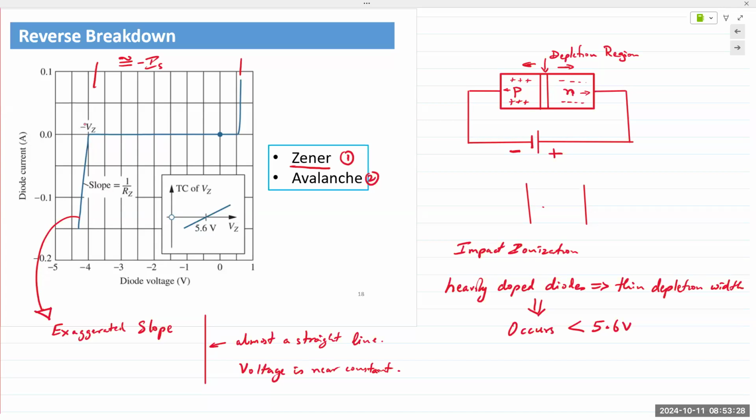The only difference is that the reverse bias PIV, we call peak inverse voltage, that each diode is able to handle increases with that number. So 1N4001 can handle up to, I think, 50 or 60 volts in the reverse breakdown before breaking down. And 4007 can handle up to, I believe, 400 volts in reverse bias.